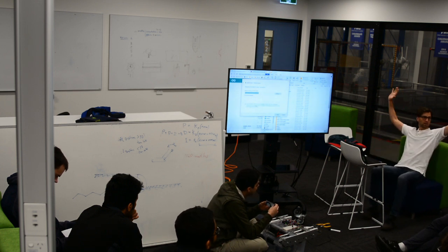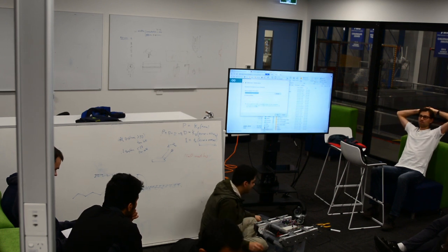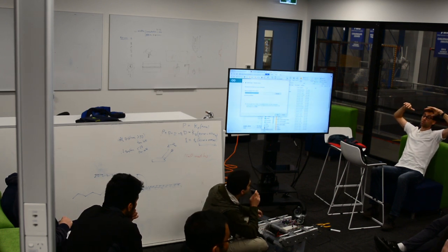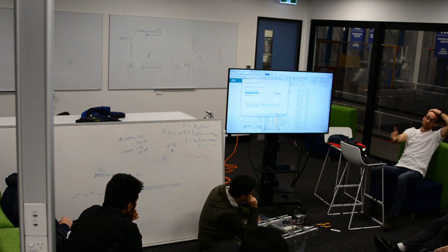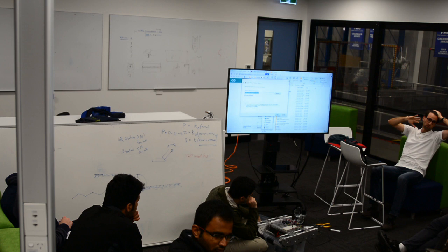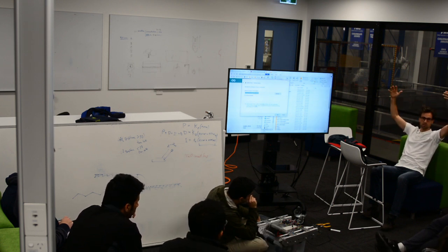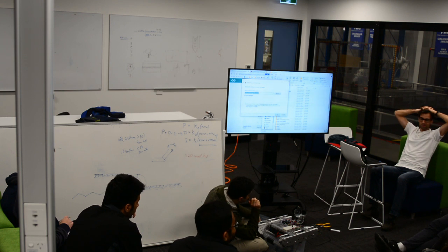Okay, I think we're gonna leave it unless someone wants to fix this, we're done. Unless there are other questions we can talk about from a theory perspective. The only thing I would say was, I think putting a D term on that might allow it to approach its target a little smoother and not overshoot, not come to such a hard stop, while still having a small amount of steady state error.